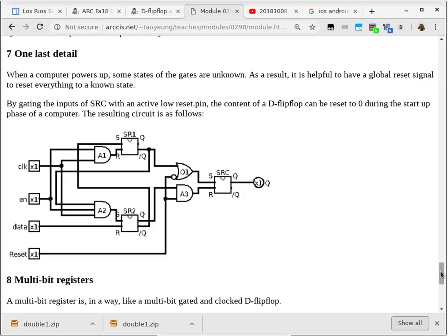It's actually a special chip on the circuit board. It's called a supervisor chip. One of its main jobs is to do a power up reset. So when it sees the power going up from a brownout level to a healthy voltage, it will hold the reset pin for X amount of time, which is usually in tens of milliseconds, which in a computer's time frame is really, really long. Most devices only take like microseconds to reset, but it will hold it on for milliseconds just to make sure that everybody has a chance to reset.